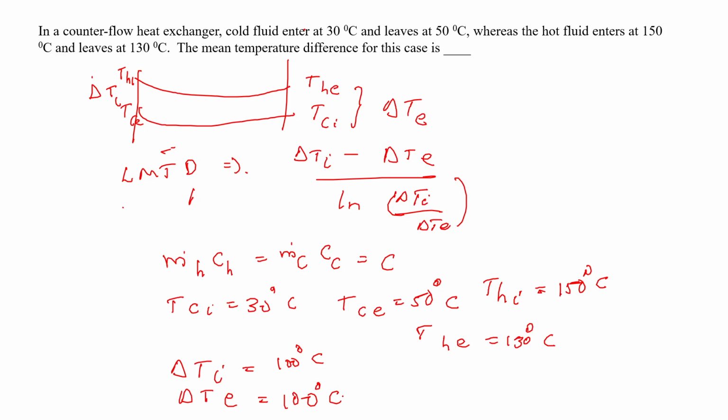This is my question, sir. Why should it not be more than 8? Is it not possible that we can design a heat exchanger with a pinch point more than 8? Yes, more than 8. In this case also it is more than 8 degrees Celsius. We cannot design the heat exchanger at a negative temperature difference between the hot fluid and cold fluid.